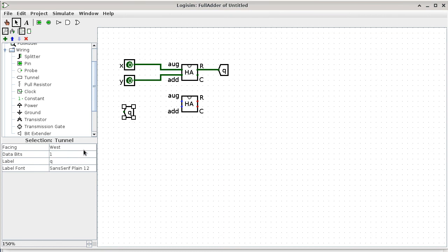With this one, I would need to change the facing first because the pointy end is where the facing is, which is also where the connection point is. This is another thing that you have to pay attention to when you draw circuits like that, because of the entire thing, there's only one point where it is making a connection logically. So you have to know where that point is, because if you draw a line and it connects to any other place of the same thing, it doesn't actually make a logical connection.